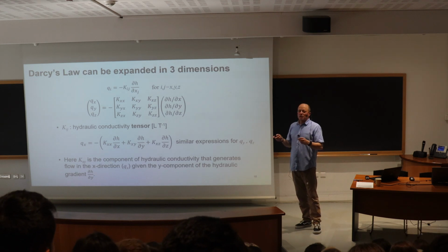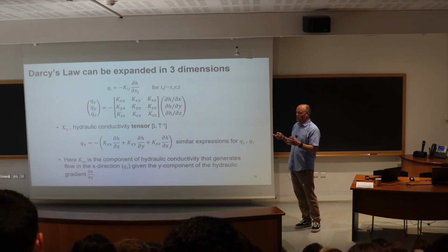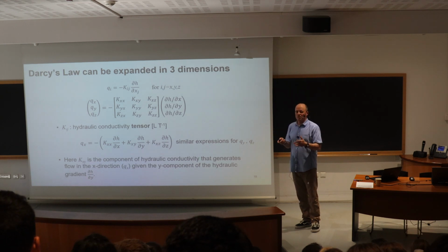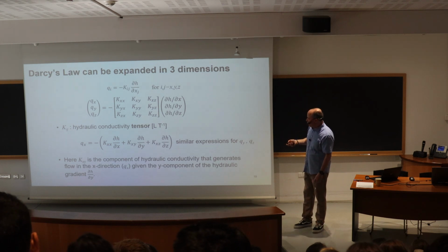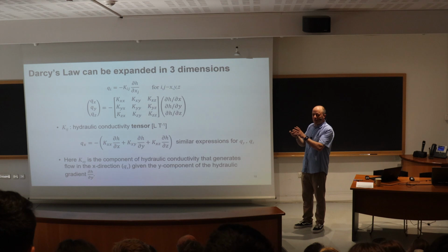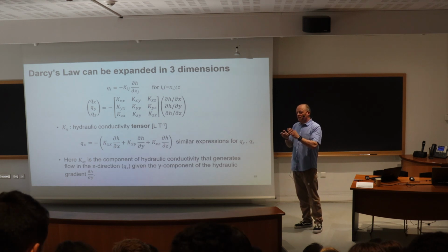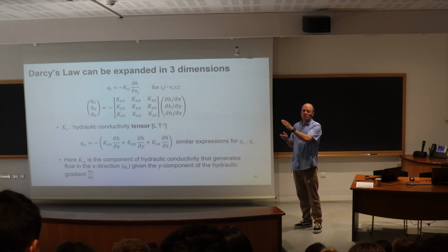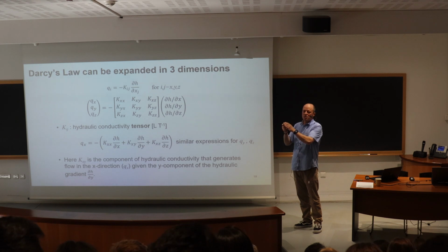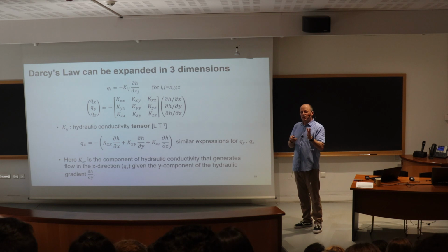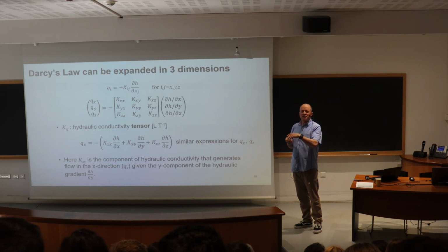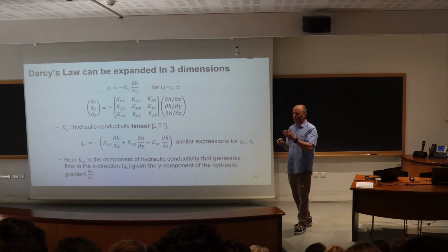So we kind of have an idea what hydraulic conductivity is. We can visualize hydraulic conductivity, but it's kind of hard to visualize what is the component of a hydraulic conductivity tensor. So we cannot measure it, we cannot see it. What I say is that because we have a 3D gradient that might be oriented in some direction in space because of pumping, because of recharge, we have Darcy flux that might be oriented in a different direction because water flows more or less easily along some directions and not necessarily along the direction of the gradient.